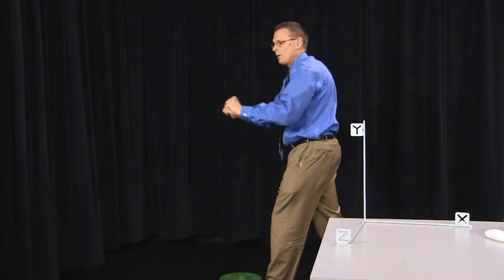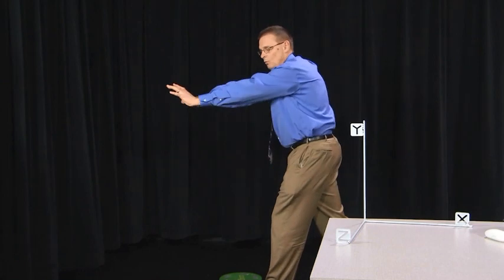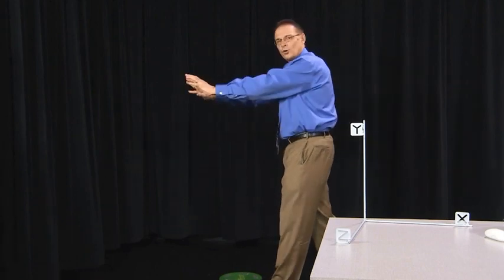Okay, so for a small automobile, if I push that with 150-pound force, and then I compare it to pushing a large vehicle with a lot of mass with the same 150-pound force, think to yourself, which vehicle will accelerate the fastest? And it should be obvious to you that the smaller vehicle, if you're applying the same force, will accelerate faster than the larger vehicle. So mass is sort of like a measure of resistance to linear acceleration. We can say the same thing for sum of the moments equals I alpha. Mass moment of inertia is a resistance to angular acceleration given the same amount of moment.